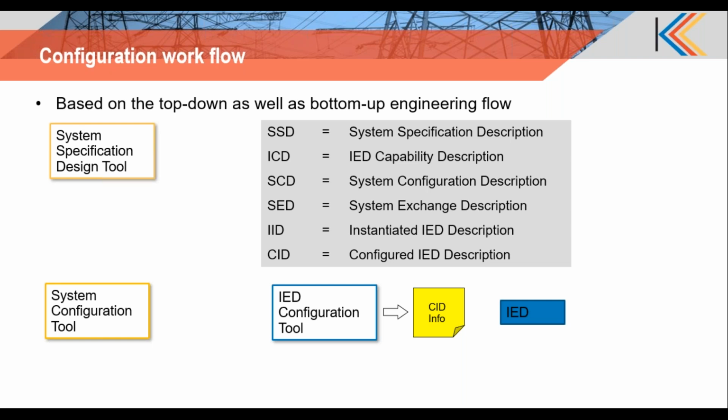But why do we really require the other tools? So the 61850 workflow specifies about three different tools. The IED configuration tool, which is actually a tool that is provided by the IED vendor. So there will be IED configuration tools specific to each vendor, and probably for different makes of devices given by the same vendor, you will see different IED configuration tools.